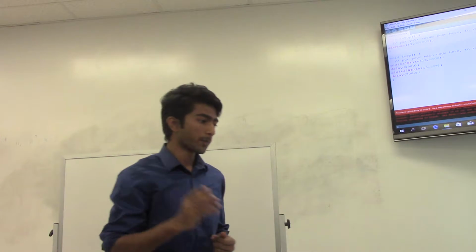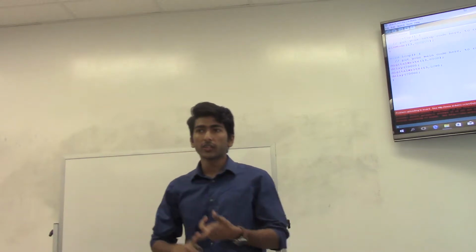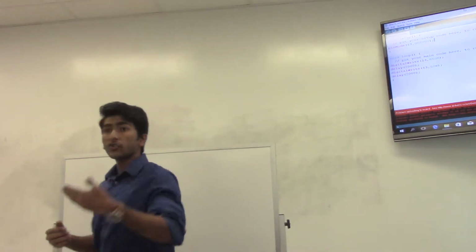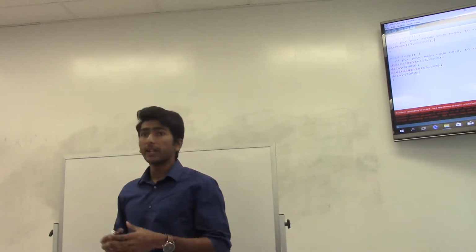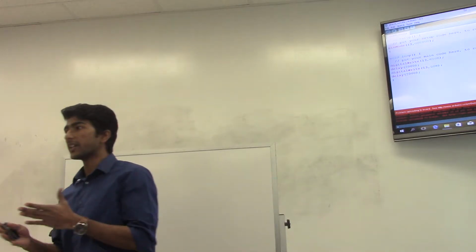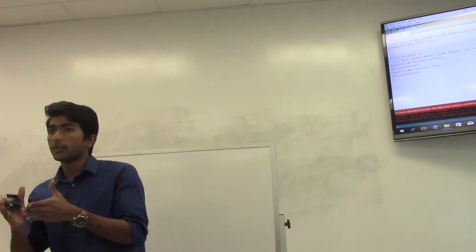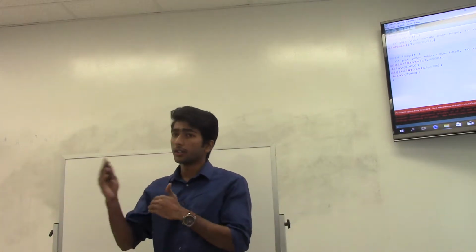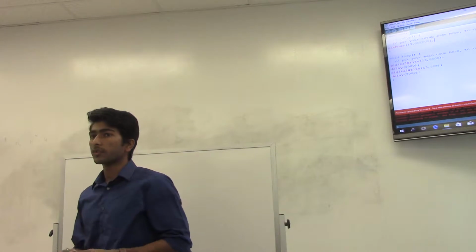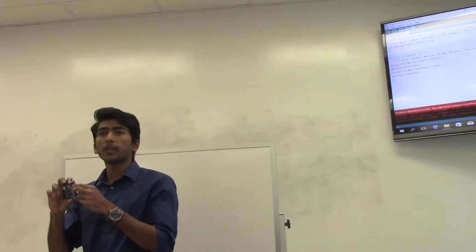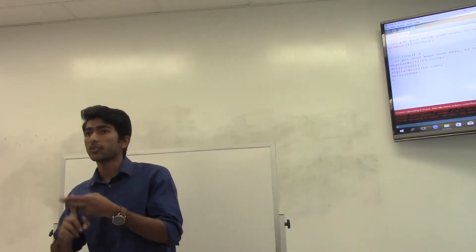And where do we use these digital pins and analog pins? When you are trying to read the sensor values such as temperature sensor, light sensor, or measuring a distance between an obstacle, you will be using analog because you will be getting the values based on the varied voltage. For example, if there is a temperature sensor that is connected to the analog pin, you will be reading a different voltage which is slightly greater than or less than, let's say, 1.5 or 1.7. So you will be able to read those fluctuations. But if you connect that to the digital pins, you will not be able to read the changes in the voltage because, as I said, there are only 2 states. Either it is on or it is off.